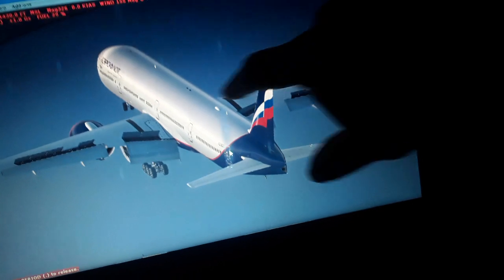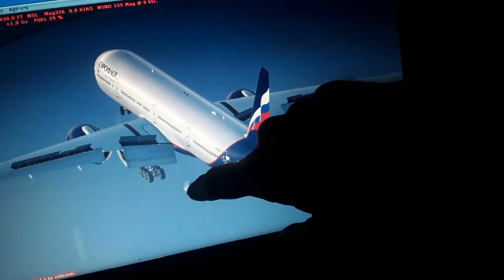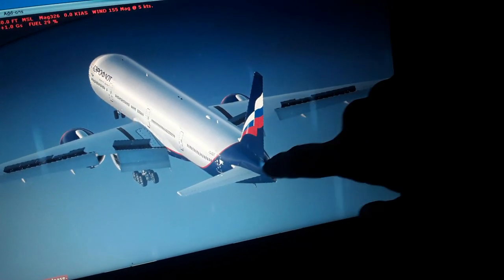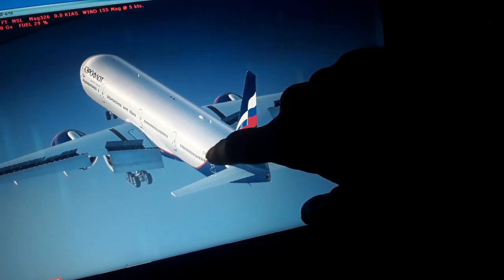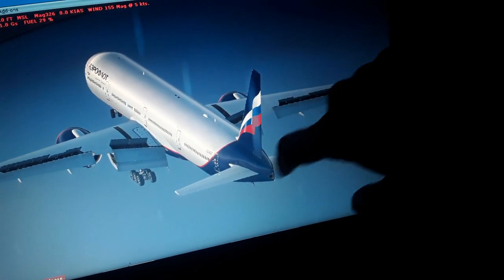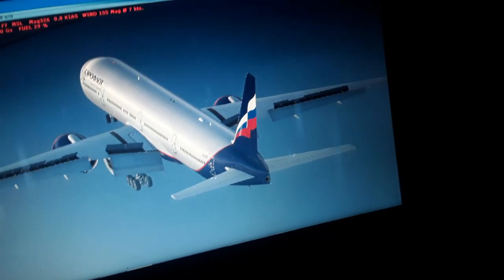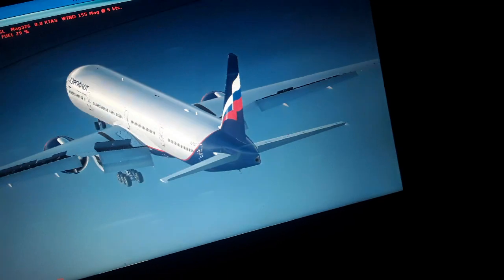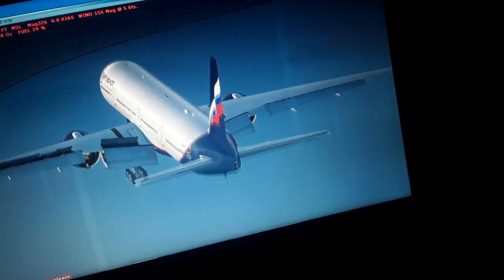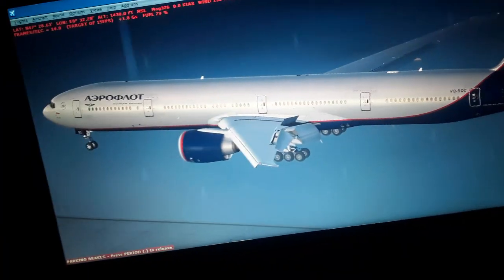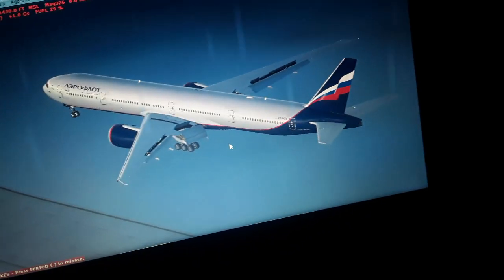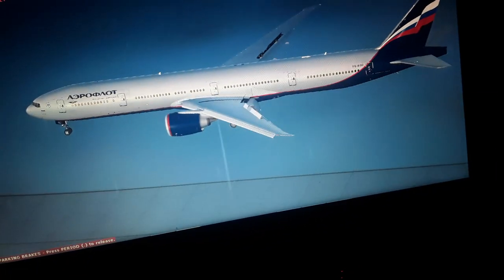So it's this distance from the center of gravity to the horizontal tail, over the horizontal tail or vertical tail surface area, times the airflow of the air mass as you fly per second, times the acceleration of gravity. So this gives the necessary force to pitch up the aircraft, through the center of gravity vector and the forward vector that traverses the fuselage all the way forward to the nose.